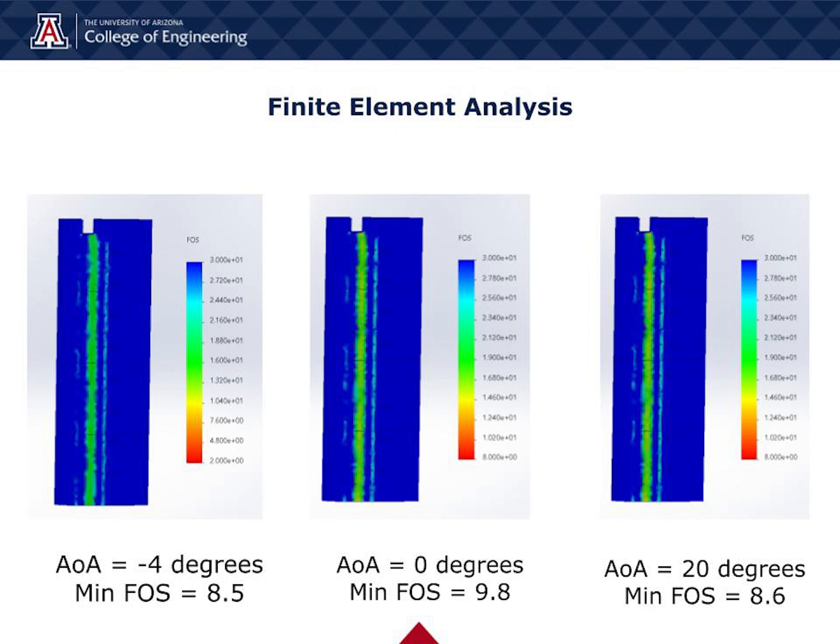SolidWorks was used to determine the maximum stresses on the airfoil and the minimum factor of safety. In SolidWorks, we ran a static analysis applying pressure loading to the internal cavity, hole walls, and the external surface of the airfoil. The minimum factor of safety of 8.5 exceeded the system requirement.